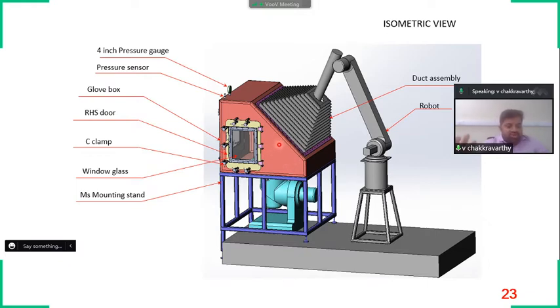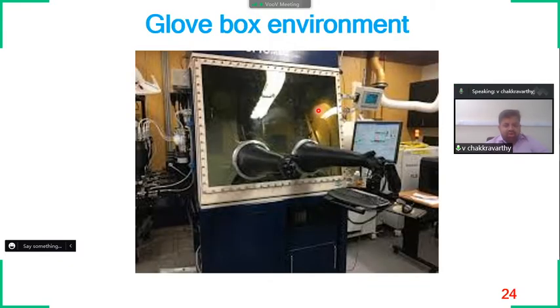It is particularly for very sensitive materials, not for all. Regularly we can build any material in an open environment. Only for sensitive materials can we go for this kind of closed chamber environment, which we generally call a glove box environment, okay. So we can see some gloves here. Only gloves can enter, because the system is completely sealed with argon gas, okay. So that is how this works. And if any weld fumes are there, they will be exhausted from a chamber here, okay, so automatically it will get exhausted. No weld fumes will stagnate, and the argon purity will remain as it is.